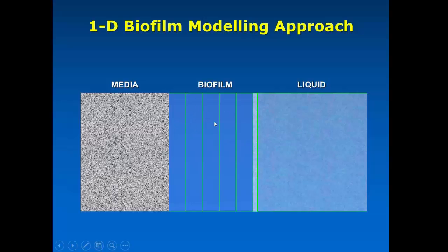And it's within each of these 5 reactors, as well as the liquid layer out here, that we actually do the calculation of the derivatives for all of the state variables that we have, and then we calculate all their concentrations, and then the composite variables, such as total COD, from there. So there's a lot going on in this model.